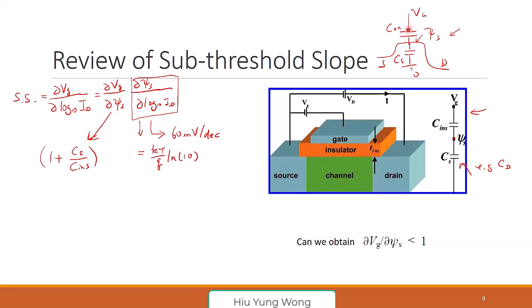Right? We can do that. But then you have a lot of leakage current. That's why we stop BJT and come to MOSFET. So this capacitor is something hurting us. There are two things. How can I increase the subthreshold slope? Well, maybe I can increase the subthreshold slope by changing kT over q. Change this physics. You can change the equation, no longer kT over q. That we will discuss later.